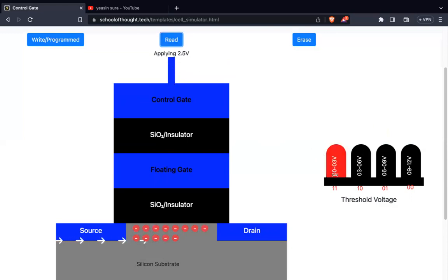As you can see, this is the threshold voltage range, which is 0 to 3 volts. So I applied 2.5. As you can see, the electrons have started to flow from source to drain. So now, as current has started to flow from source to drain, we can easily say that a 1 has been stored. That stored information is 1 1, right?